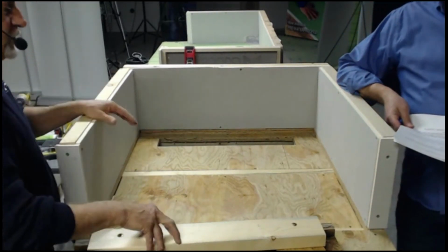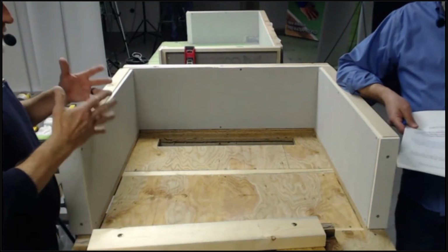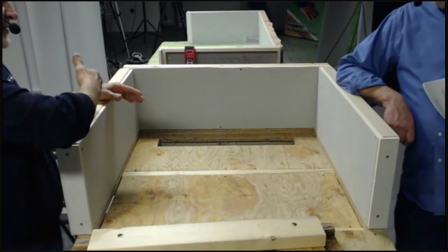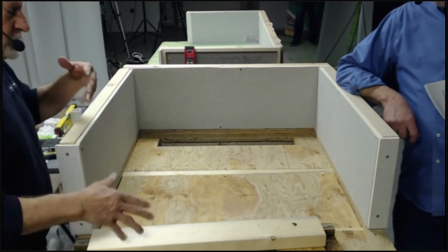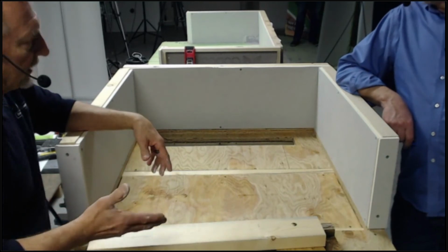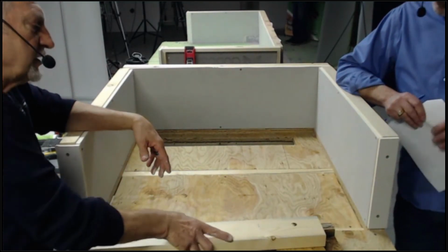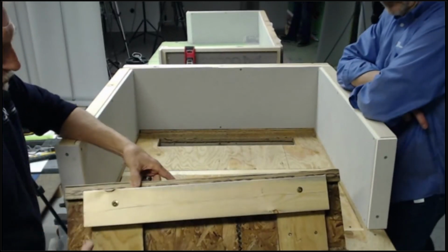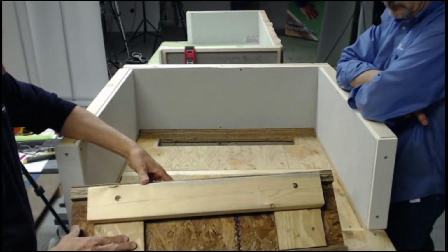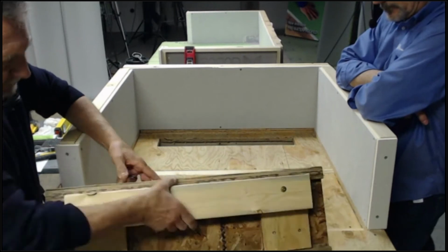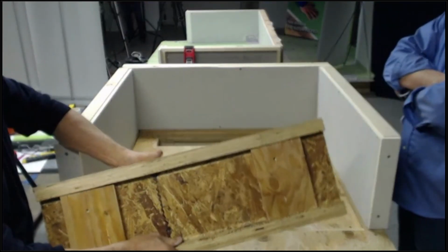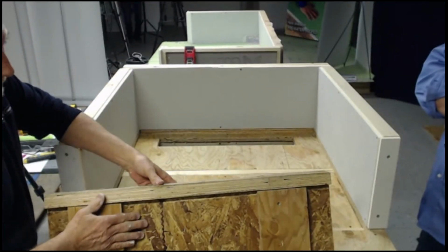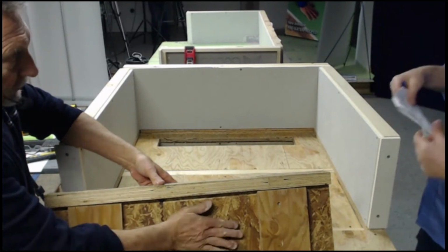One thing I did want to touch on, you've seen the typical dimensional lumber, 2x8s, 2x10s, floor joists. If you have a case where you have BCIs, I-joists, it's a little bit different installation. With I-joists, you're going to have to use blocking in here. As you can see, I have blocking sandwiched in between my bottom and top structural flanges.